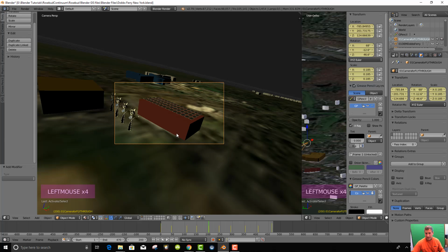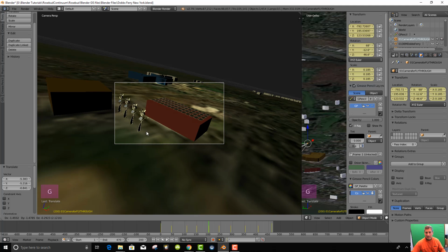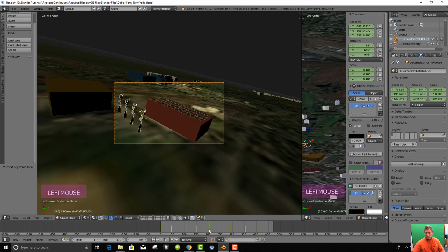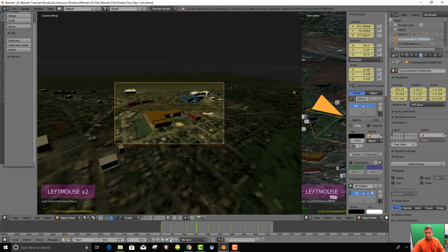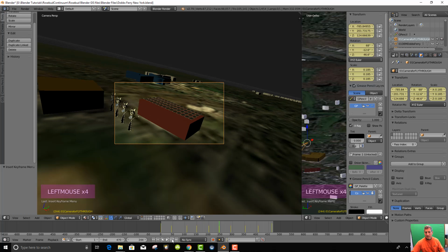This here jumps to that keyframe, and we can change that keyframe by using the G key. Now that that keyframe is there, we can set it, location, rotation, scale, and replace that keyframe. So when it stops on that keyframe, all of the windmills are included. That next keyframe we don't need.